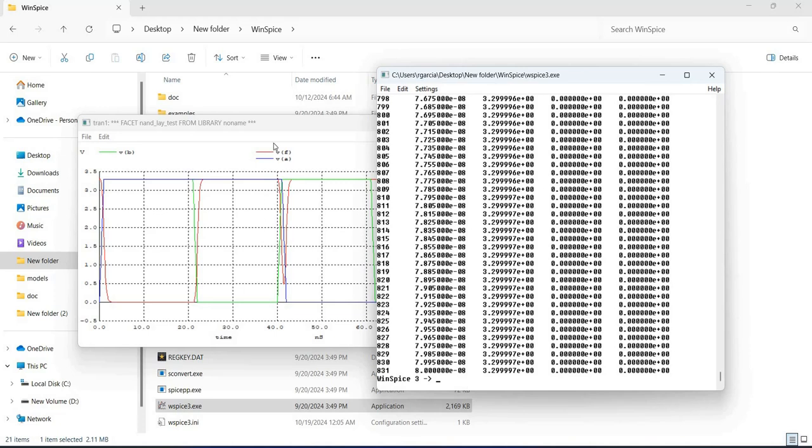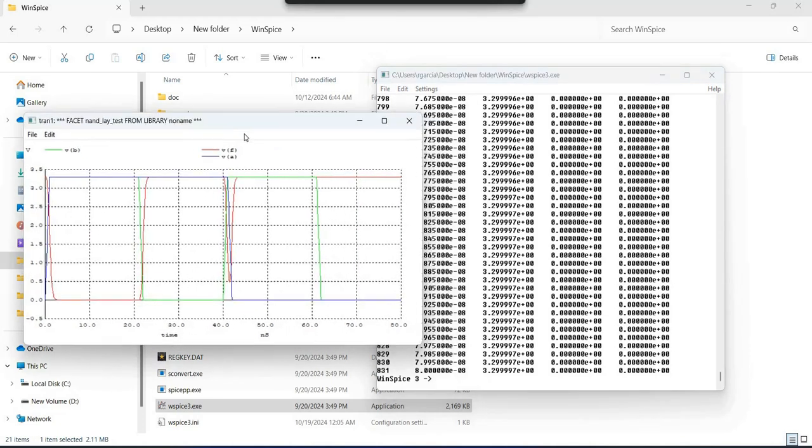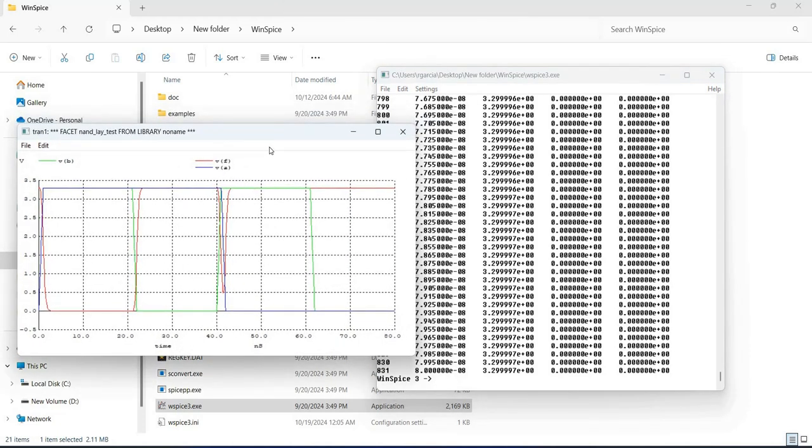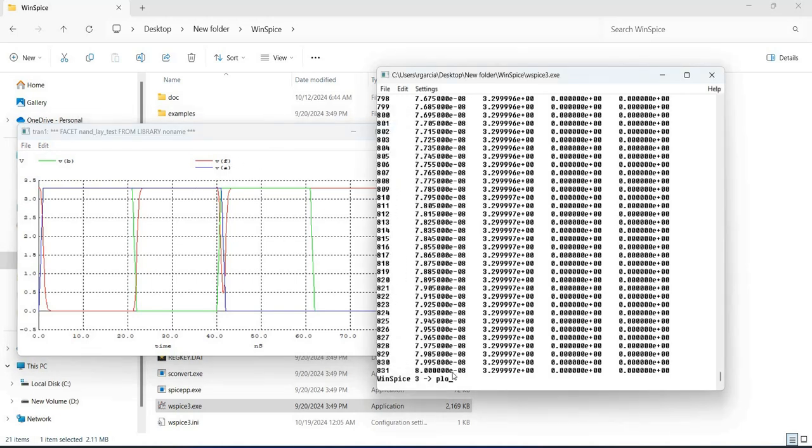For you to properly see the graphs, you can arrange it in such a way that A will be assigned as the most significant bit and F as your output. So you can just use plot VF VB plus 4, and on the top of your plot will be A, so that will be plus 8.